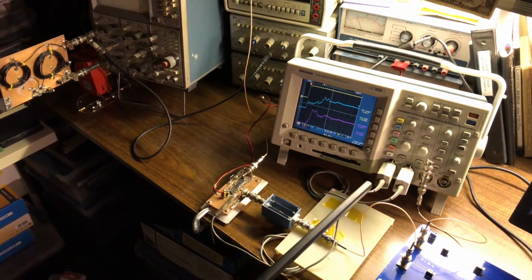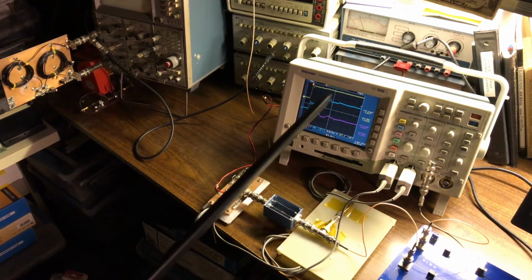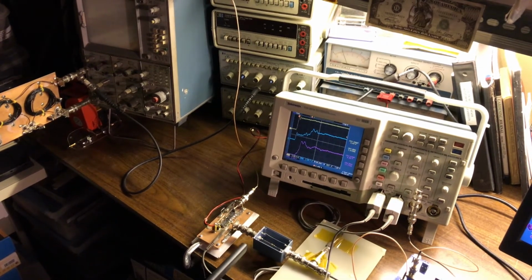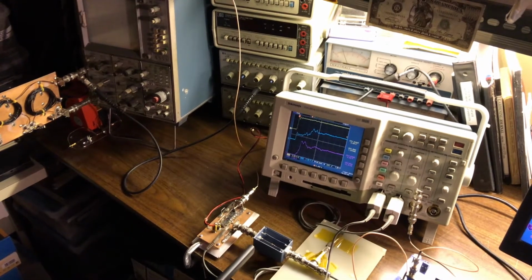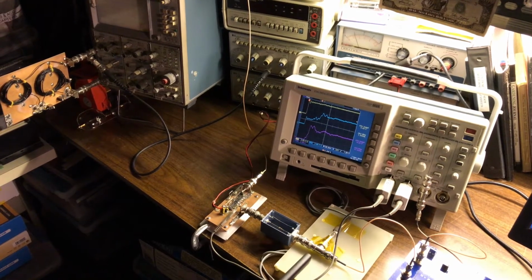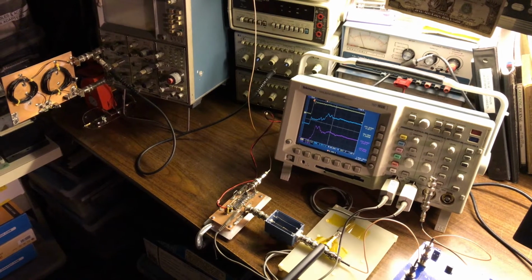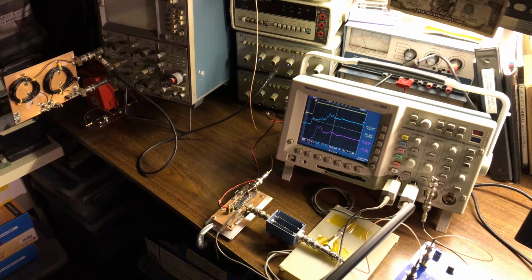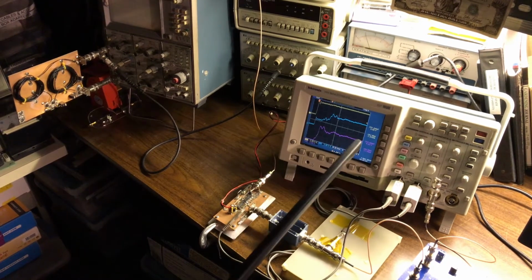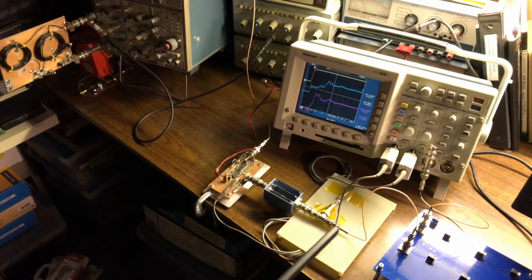input 1 of the oscilloscope, which is the yellow trace, and then follows at the output of the low impedance driver. There is a source termination resistor, 50 ohms, and there is a tap here for a probe that takes the signal into input 2 of the oscilloscope, which is the blue trace,